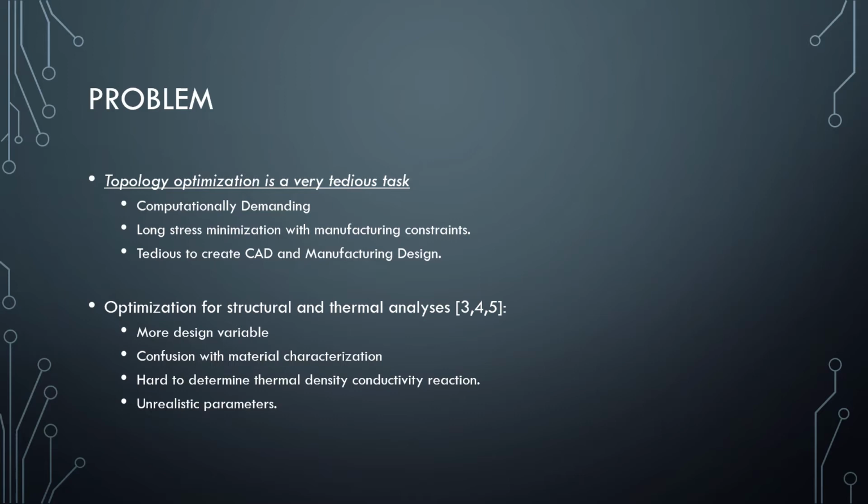On top of that, it is very tedious to convert an optimized topology design into a computer-aided design-friendly and/or manufacturing-friendly product. Also, the optimization for structural and thermal analysis has some complications too, such as more design variables, confusion with the material characteristics, difficulty determining the thermal conductivity, as well as unrealistic parameters.